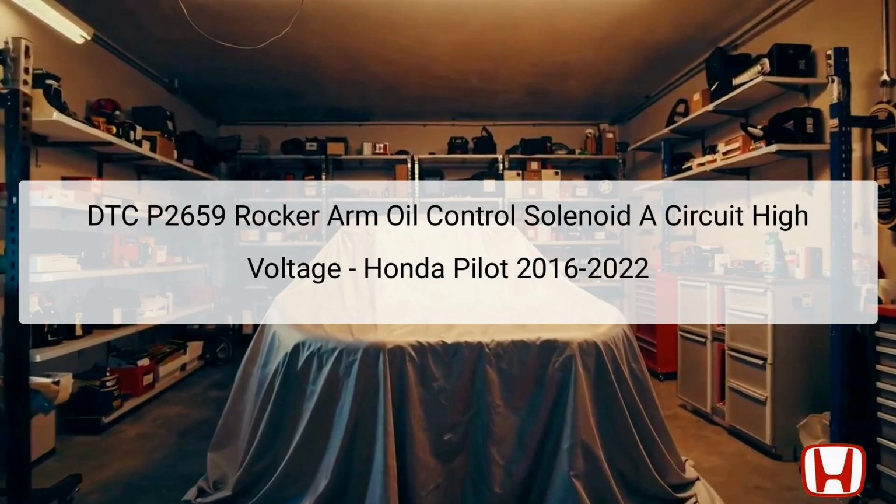The rocker arm oil control solenoid plays a vital role in controlling the timing of oil flow to the rocker arms, which is essential for variable valve timing (VVT) operation. This solenoid aids in regulating engine performance by optimizing the valve timing according to various driving conditions. A malfunctioning rocker arm oil control solenoid can lead to decreased engine efficiency, increased emissions, and potential engine damage. Understanding this DTC and carrying out the necessary troubleshooting steps is critical for restoring optimal vehicle performance.